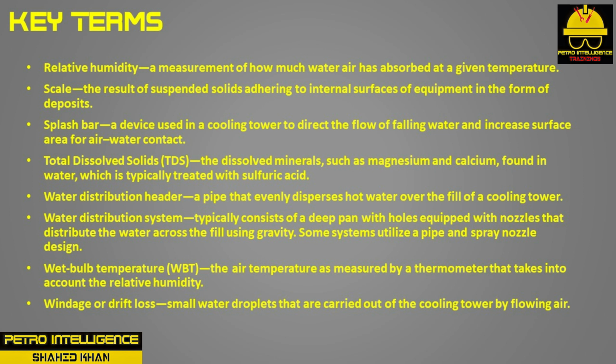Water distribution header is a pipe that evenly disperses hot water over the fill of a cooling tower. Water distribution system typically consists of a deep pan with holes equipped with nozzles that distribute the water across the fill using gravity. Some systems utilize a pipe and spray nozzle design.